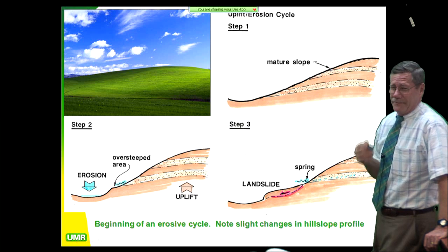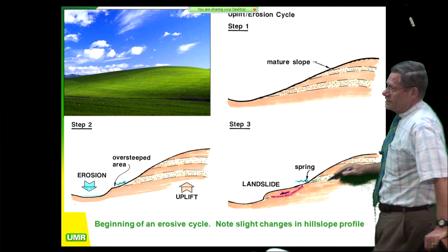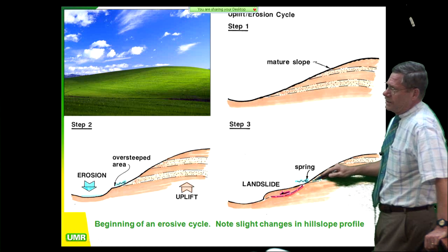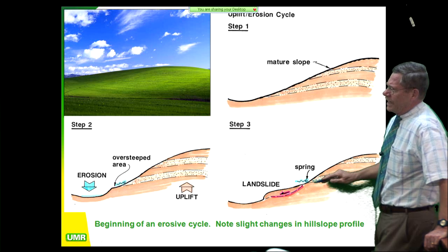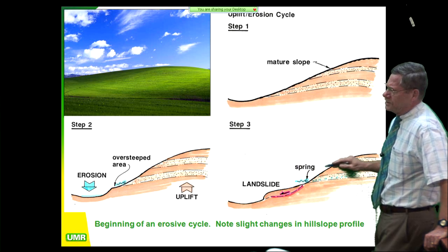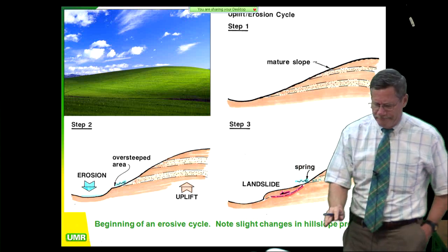But if you went out there after 3 months of near constant drizzle, you might see an ephemeral spring, but usually they're under the ground. Usually you don't see them. What is real nice is geophysics. Use spontaneous potential, you'll find the wet spots, because they have high conductance.